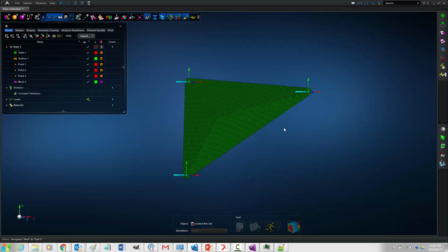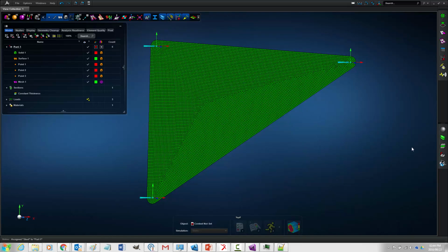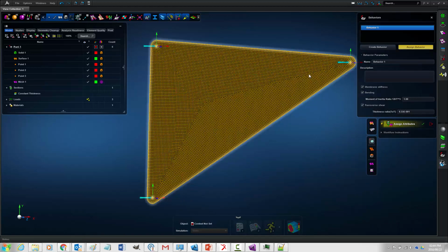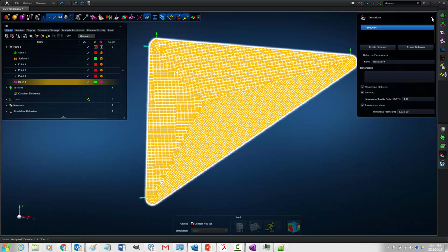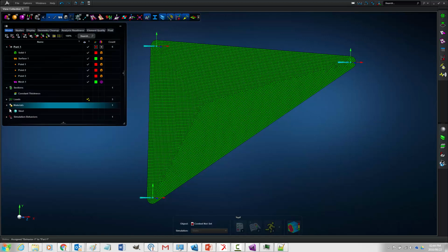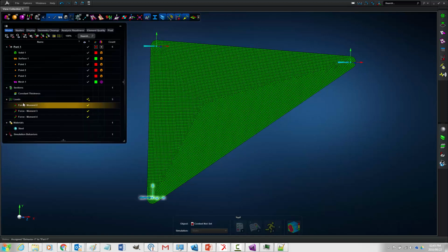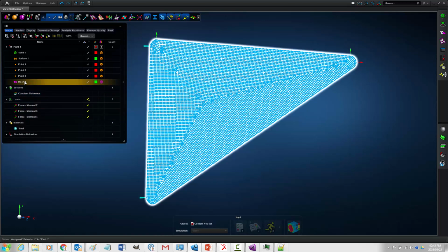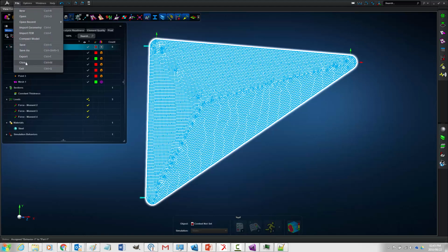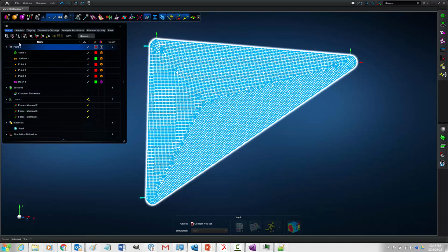One other step that I just need to specify is the bending stiffness behavior. Purely just assign it over here, and this is just to complete the picture that we have a bending stiffness behavior, we have a material assigned, we have temporary loads assigned, we have a thickness assigned, and we have our mesh. Now we're going to export the mesh, and we can do this at the part level or at the file level, because at the file level we only have this single part, so it really doesn't matter which option you choose.